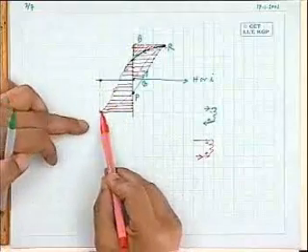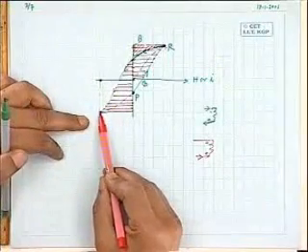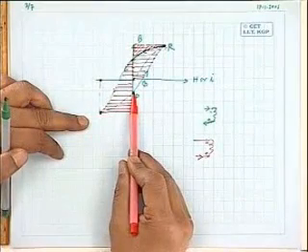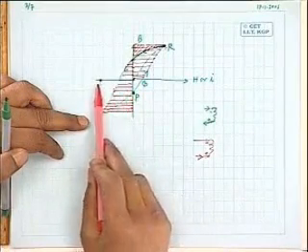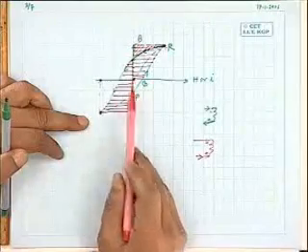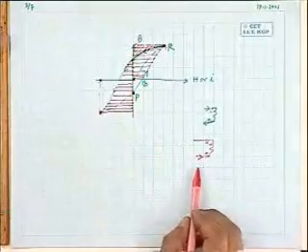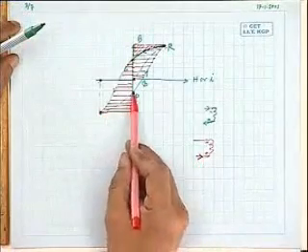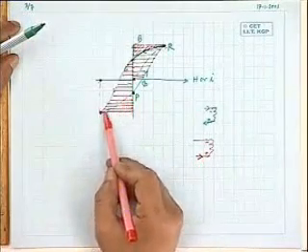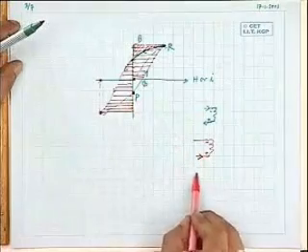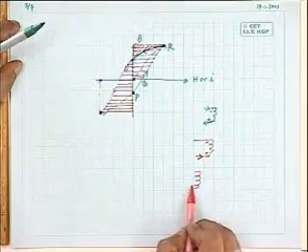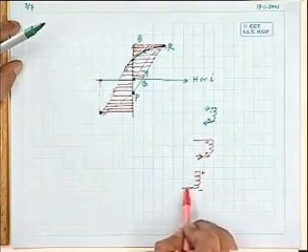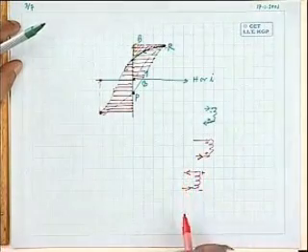So it reaches this point now. Then once again, when current comes down from I max to 0, H changes from H max to 0, then current direction still remains negative. But what happens is this dB/dt becomes positive here, from this to this. So the situation will be like this: coil, this is plus, this is minus, and current is negative.